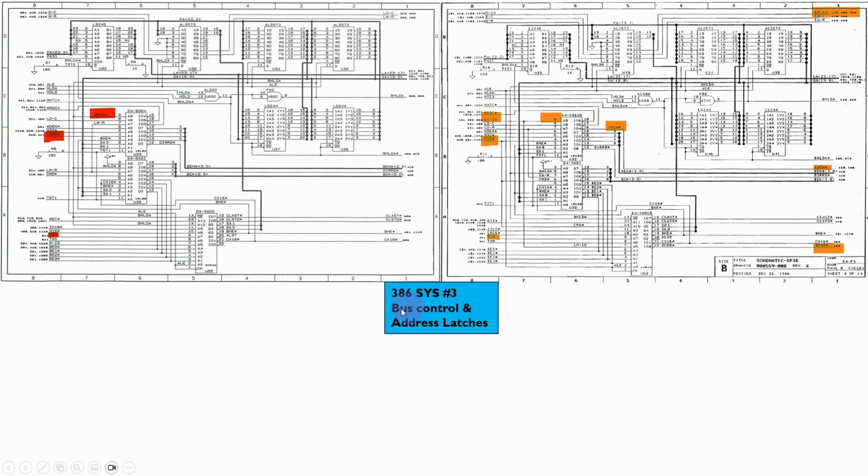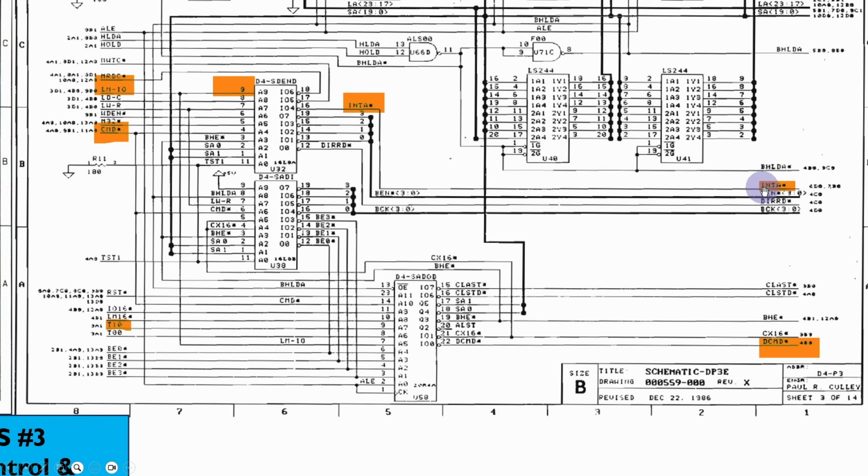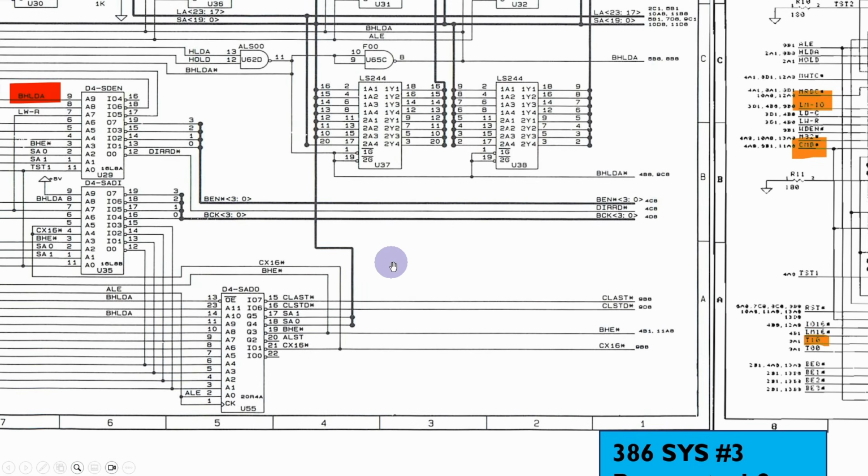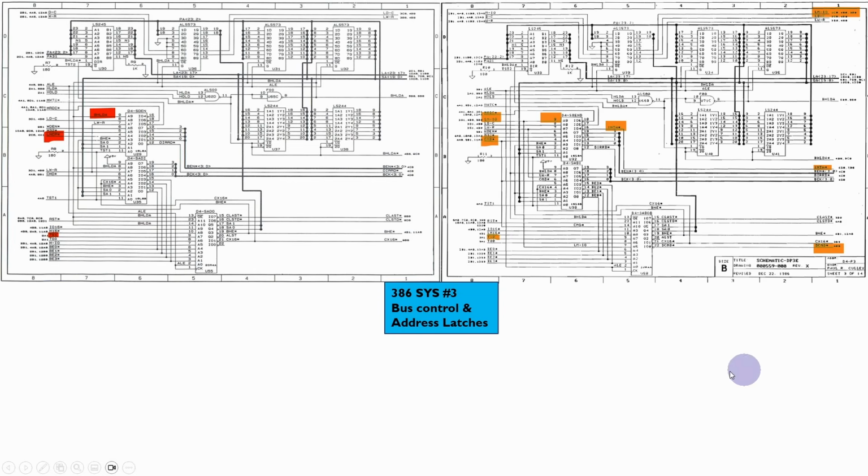So on the next one, on SIS3, there are a few differences. You'll notice that some of the labels and things, the timing for example, rather than using certain signals, they've been replaced by others, and also where the output of certain things comes from. So for example, you'll see over here that the interrupt acknowledge signal is now coming out of this chip over here, whereas previously interrupt acknowledge isn't in here. So they obviously cleaned up the board somewhat and moved certain signals around.